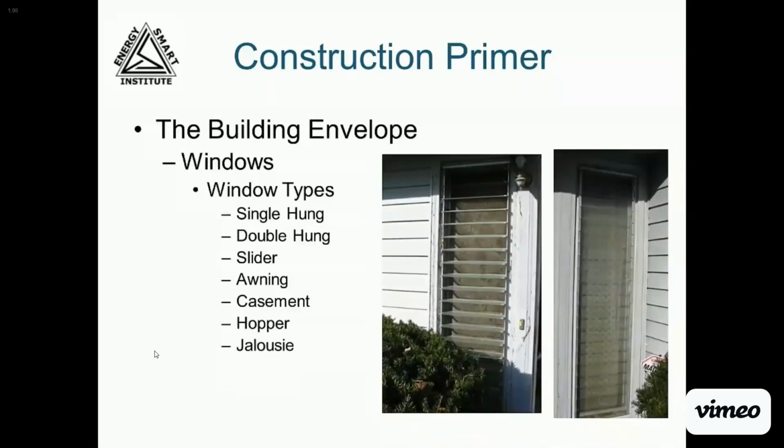The jalousie window is likely the least energy efficient window. It's made up of several small panes of glass that overlap each other horizontally and crank open in unison. It's impossible to close this window tightly since the glass panes are overlapping. Interior storm window kits are about the only way to manage this leakage in the hot and cold seasons.